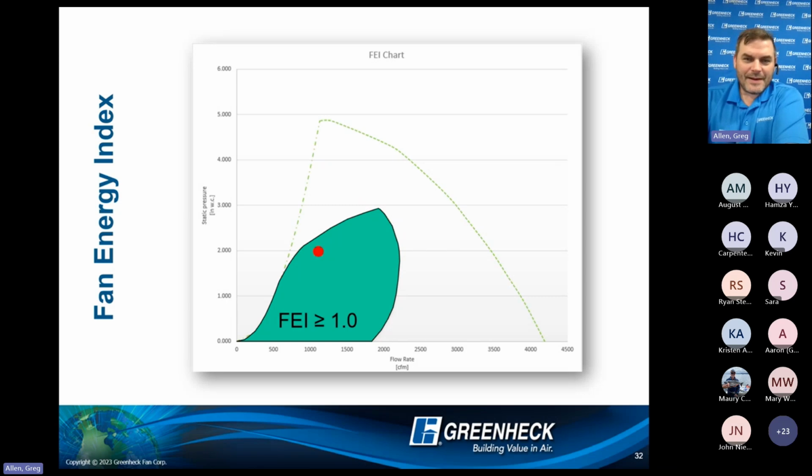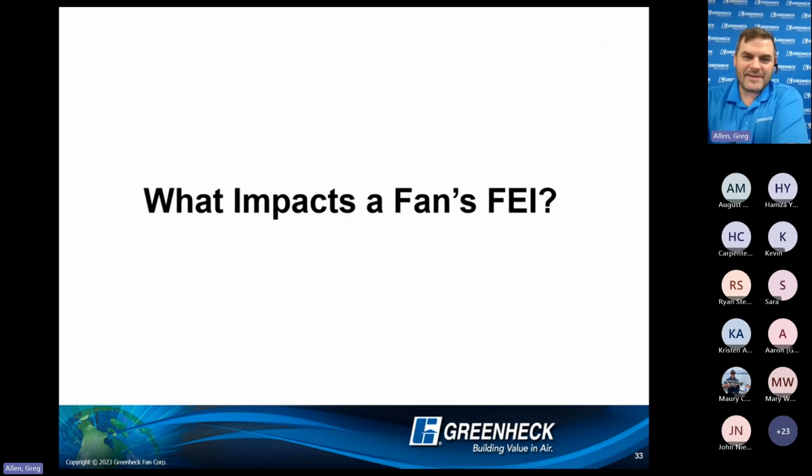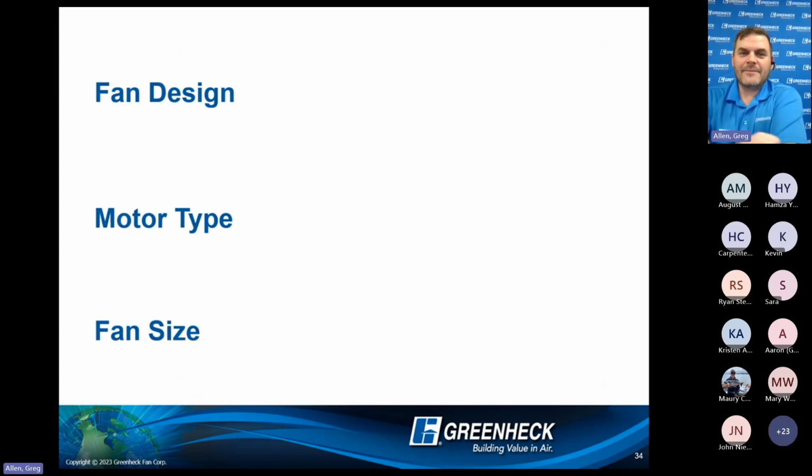Okay. All right. FEI's impact. So when I'm looking at fan energy index, incorporating it into our design process, whether you're designing the building or even me as a manufacturer, there's really 3 areas that it's going to hit, and that's fan design, motor type, and fan size.